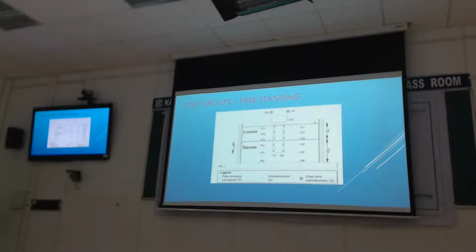So the first set of tests we did were with all the piles standing free of the surface. So we have loose sand, dense sand, and the piles going into the dense sand, and the pile cap is clear of the surface. So there's no question of any pile cap capacity here. Basically, we've done what the designers are already considering, took the soil away. So there's no doubt. So that is the first series of tests we did.